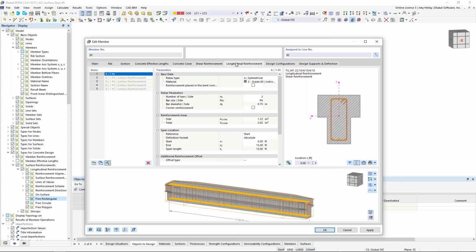For the longitudinal reinforcement, notice we have some grayed out options here. So what does this refer to? Well, if I take a look along the length of the member, we can actually consider automatically the surface reinforcement. Remember those number 5s at 12 inches on center that we defined? You can see them displayed here in the effective widths or the flanges. Well, we can also turn this off and manually apply reinforcement as well, which is what we'll be doing today. So we'll begin first with the basic longitudinal reinforcement here within the main member.